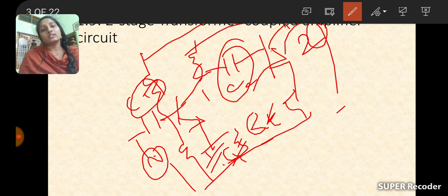And coming to the transistor T2 also, in the same way the resistances R1, R2 act like a stabilization network. So stabilization means the output is constant irrespective of variations in the input. And here the emitter bypass capacitor and the resistor are connected in parallel, and those are indicated with RE and CE. It will provide a low reactance path to the amplified signal. And this is the construction.